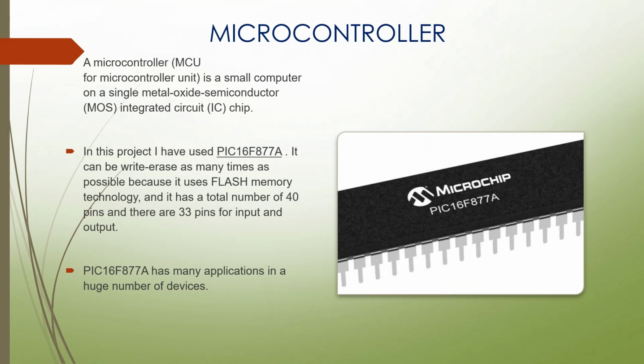A microcontroller is a small computer on a single metal oxide semiconductor integrated circuit chip. In this project, I have used PIC16F877A. It can be written and erased as many times as possible because it uses flash memory technology, and it has a total number of 40 pins, and there are 33 pins for input and output. PIC16F877A has many applications in a huge number of devices.